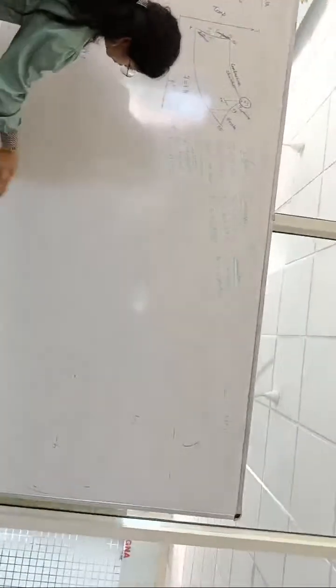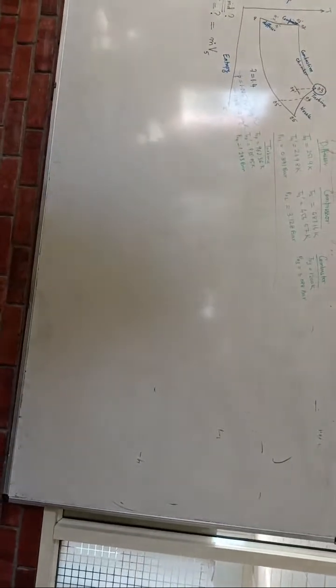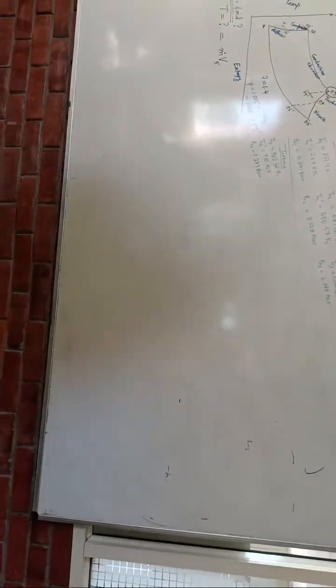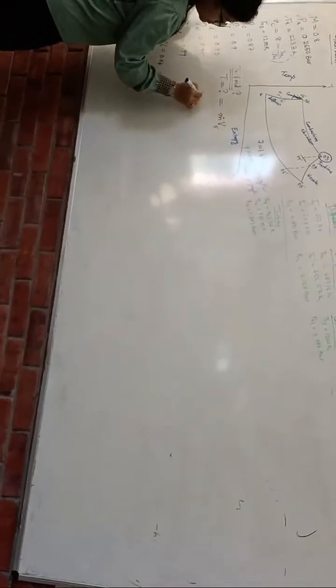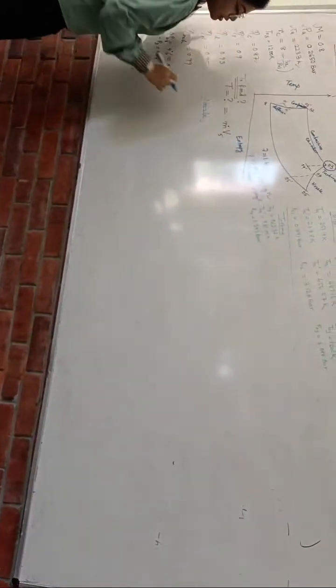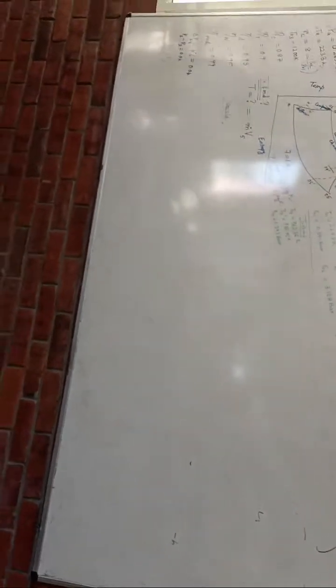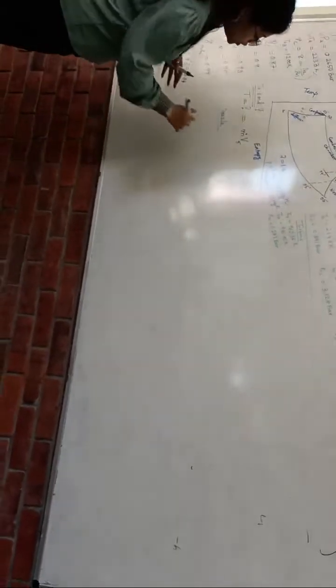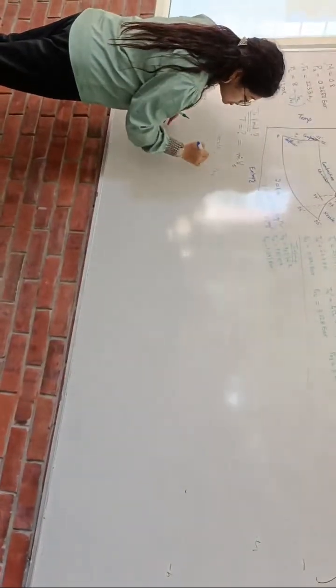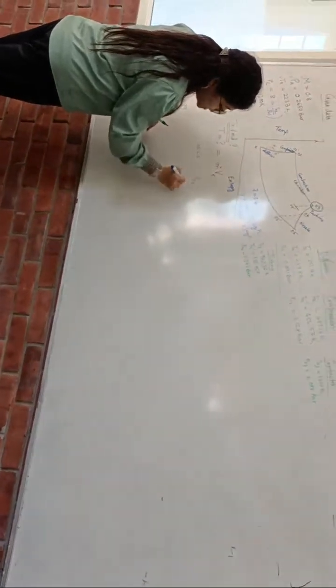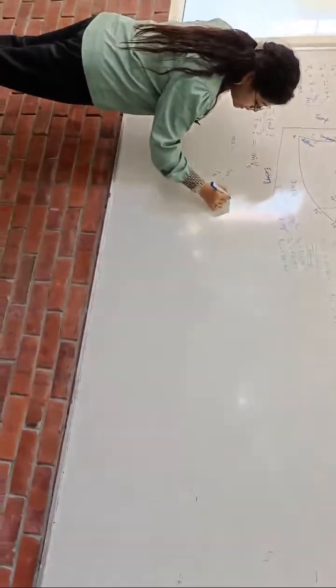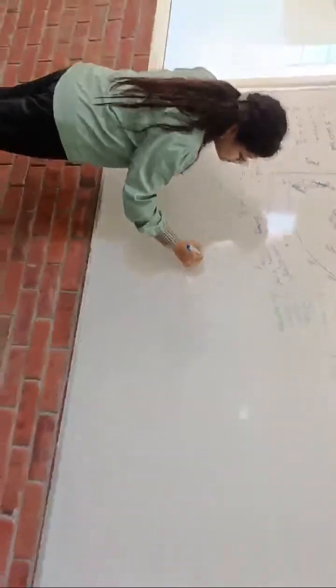When we are going into the nozzle component, first and foremost we have to identify whether this nozzle is choked or not. So what is the formula for this? The choking condition: P naught 4 by PA has to be greater than P naught 4 by PC.